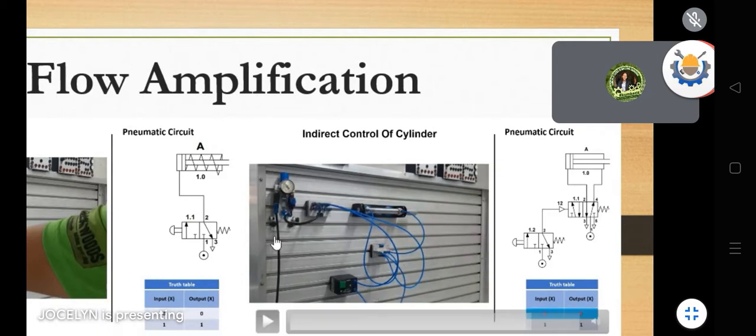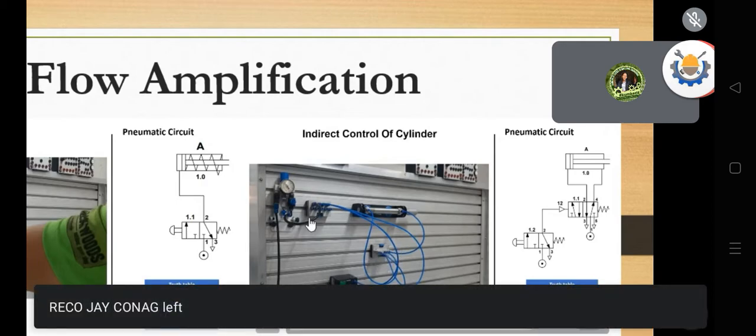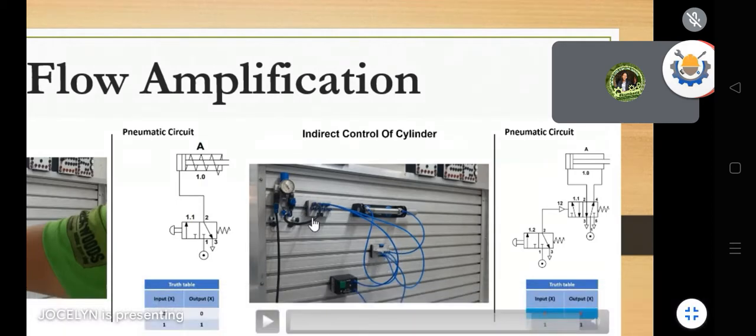Earlier, it was not shown. That earlier one was for the two valves, then this one is the straight direct actuation. From this one, it goes directly to number 1, to air pressure, our air compressor. Then port 2 is connected to the extraction, and port 4 is connected to the retraction, retract. And port 1 is for your air pressure.